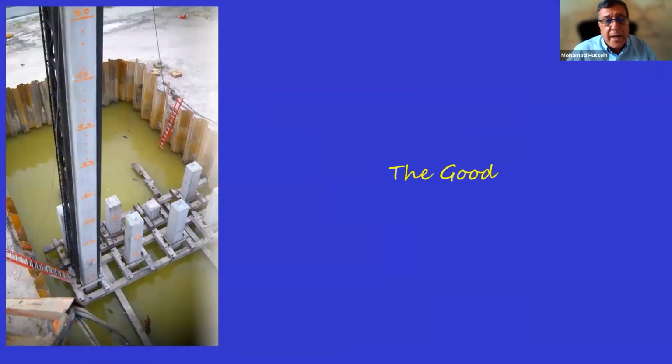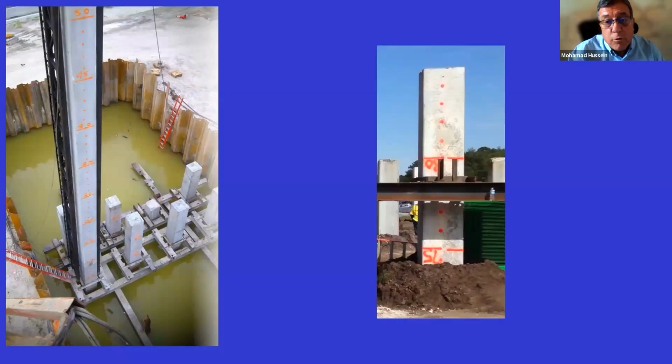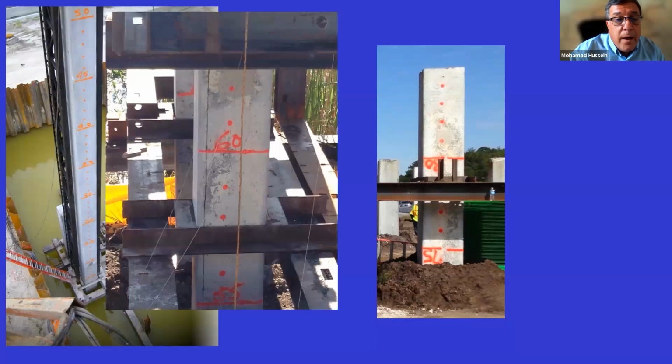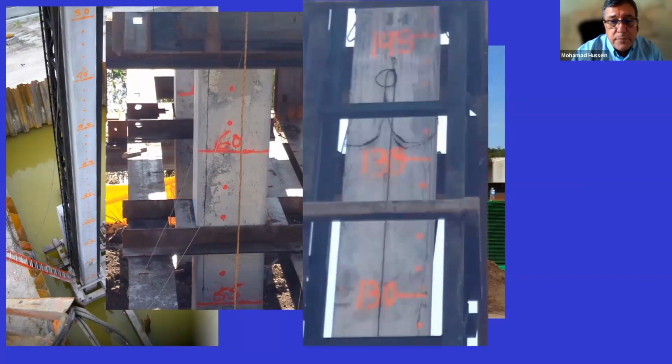Now, to apply all that, the pile has to be marked properly, as this pile is beautifully marked. It's driven upright. It looks good. Not always. This pile is driven upside down. Notice the length of the foot in this case between 59 and 60 feet, and the foot between 60 and 61 feet. Obviously the blow count per foot here will not be very meaningful.